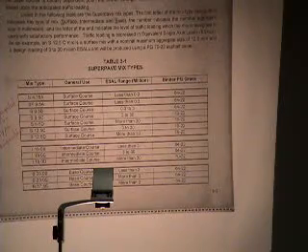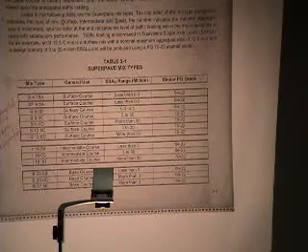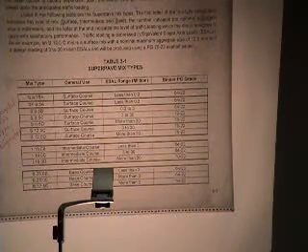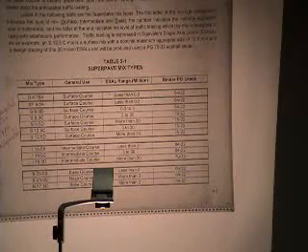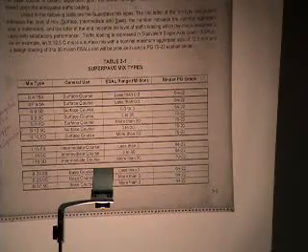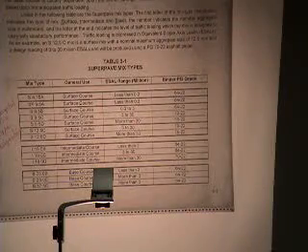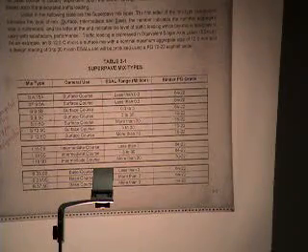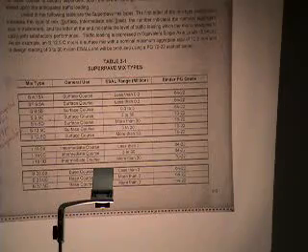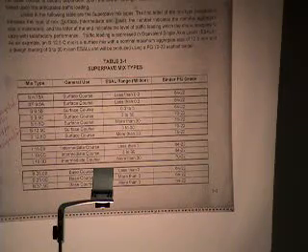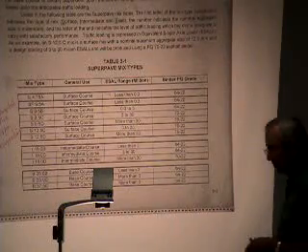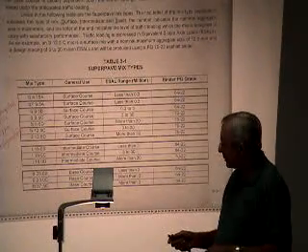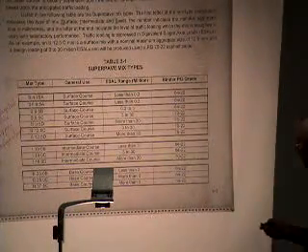You have to consider that, and if you can justify the cost of it, it is a very high performance asphalt. But otherwise, you wouldn't want to use it because there's no gain, as far as rutting resistance on low traffic roads, so you wouldn't want to use it. So those are our three basic types and background on how those mix types are selected.